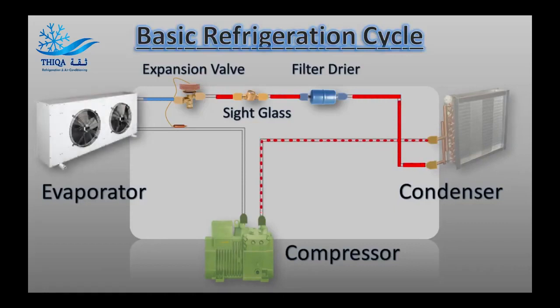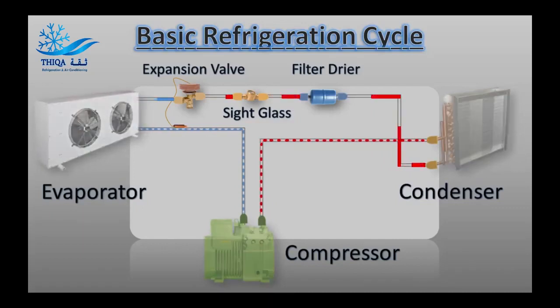the evaporator as a low-temperature liquid at low pressure, and a fan forces air across the evaporator's fins, cooling the air by absorbing the heat from the space in question into the refrigerant. After doing so, the refrigerant is sent back to the compressor, where the process restarts. And that, in a nutshell, is how a refrigeration loop works.